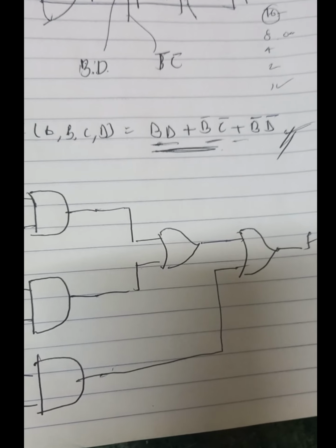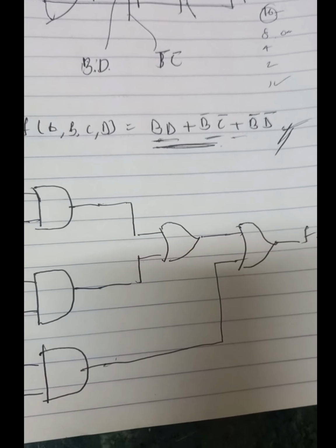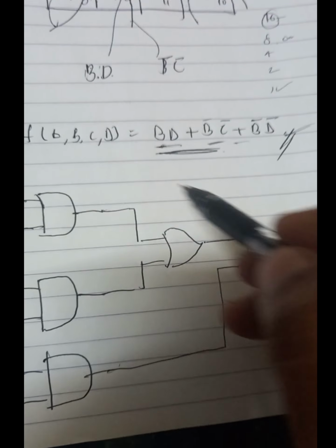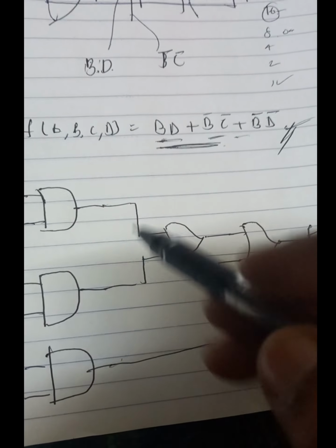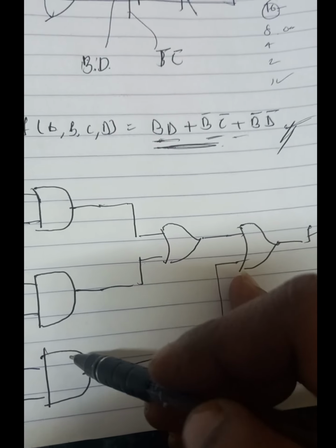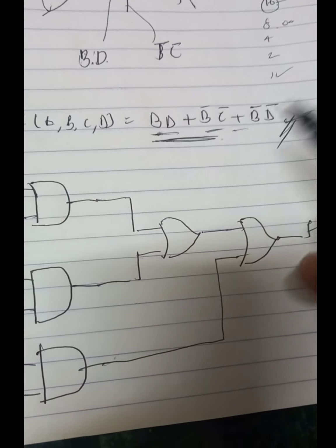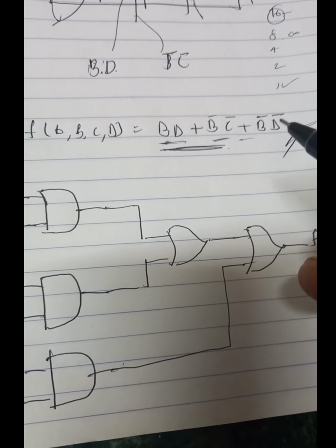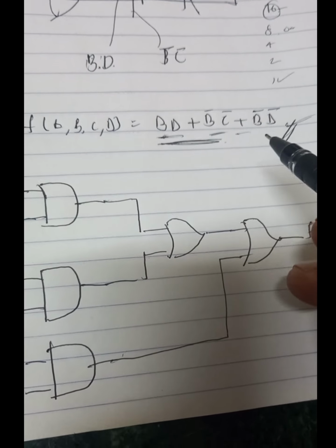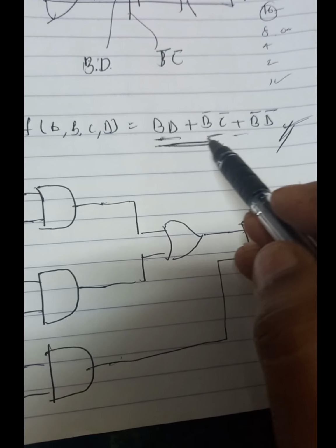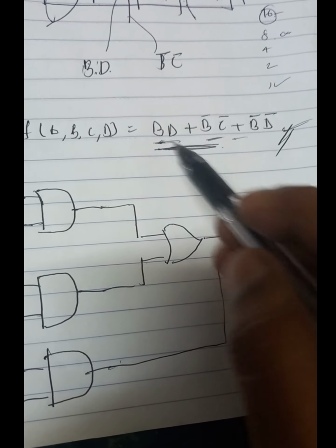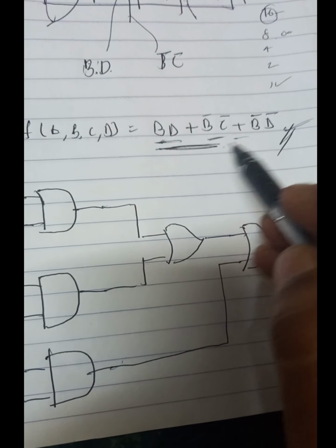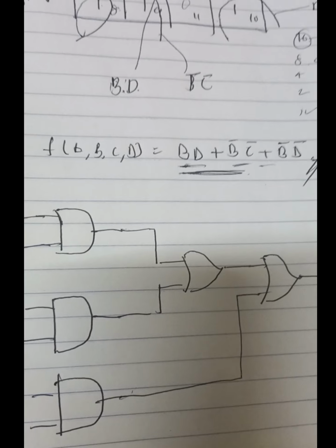I can write different types of Verilog code, as a structural or data flow model. With structural or gate level modeling, while seeing the simplified figure, I can write it with the three AND gates and two OR gates, or else directly with the data flow model, or else I can use the behavioral model. We'll see how to write the program for this.